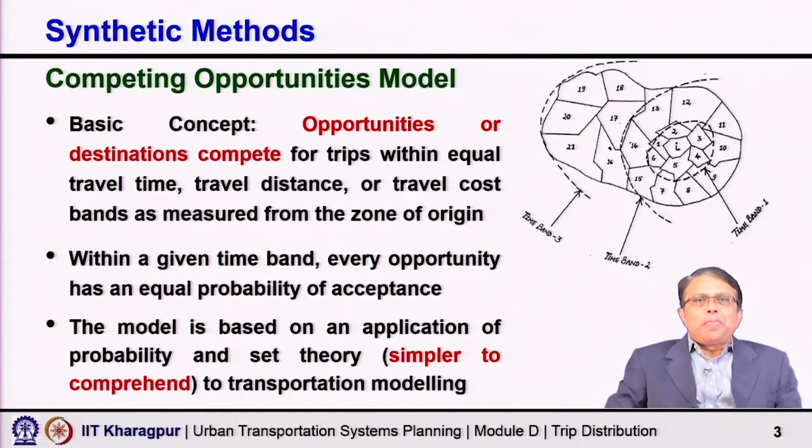Let us come to the competing opportunities model. You are already familiar with the term opportunity, or you have already studied the opportunity model. The new thing here is competing opportunity. So, what is competing? Who are competing? The basic concept here is that opportunities or destinations compete for trips with equal travel time or travel distance or travel cost bands as measured from the zone of origin.